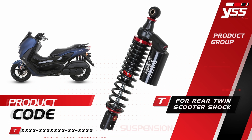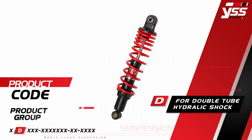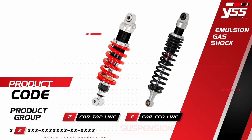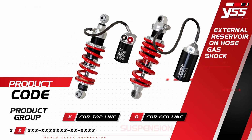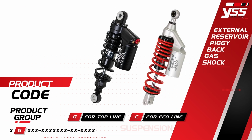Digit 2. Product type. S: Single tube hydraulic shock. D: Double tube hydraulic shock. B: Double tube gas shock. Z: Emulsion gas shock, Z for top line or E for eco line. A: Divided piston gas shock. X: External reservoir on hose gas shock, X for top line or O for eco line. U: Bottom external reservoir piggyback gas shock, U for top line or K for eco line. G: External reservoir piggyback gas shock, G for top line or C for eco line.